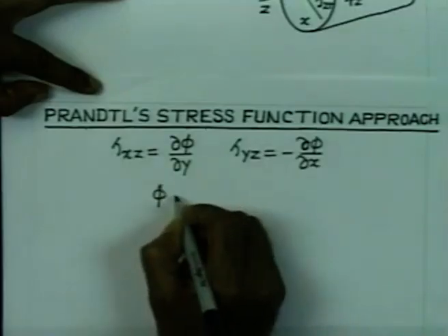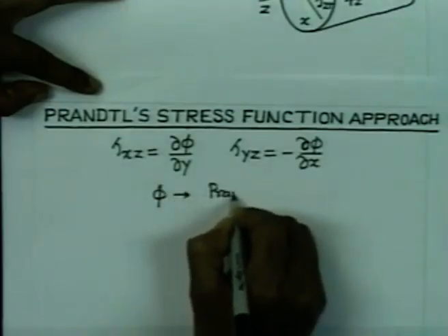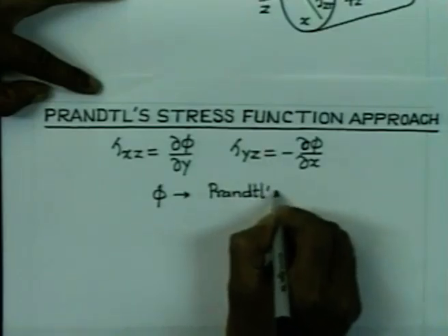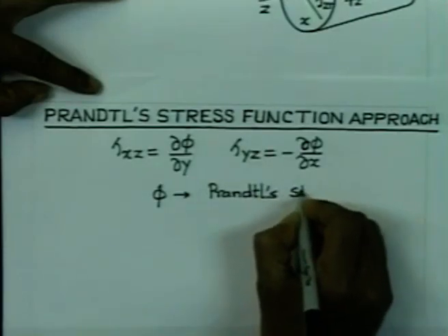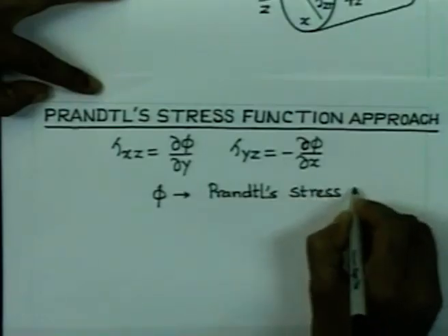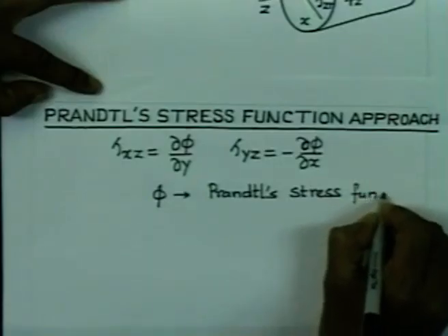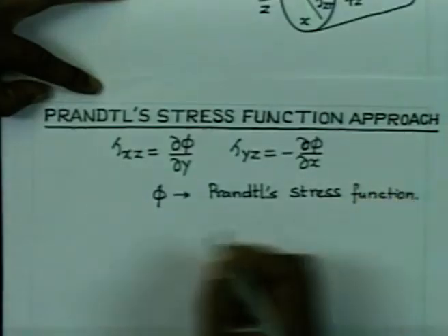So, phi is the Prandtl stress function. Now, we can get some relationship between this Prandtl stress function and also the Saint-Venant warping function, and it is possible to also comment on the properties of the Prandtl stress function looking into the physics of the problem.